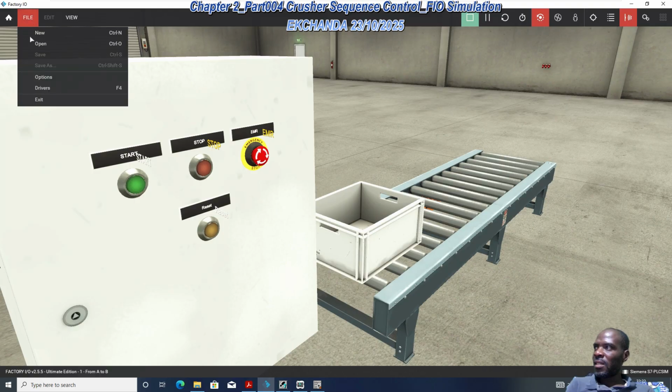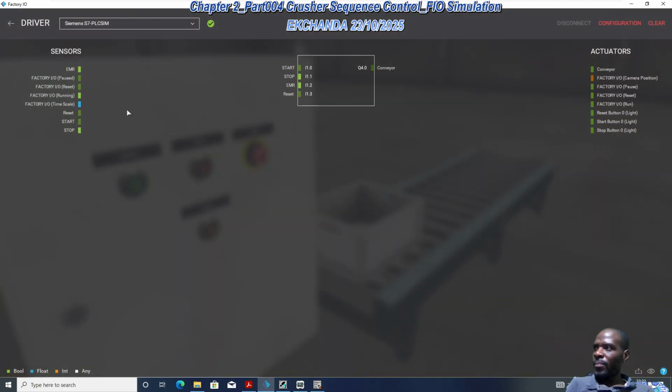If you noticed here, okay, if I press the emergency push button, it sustained the change in state, okay, unless of course I reset, then the status is normalized, as opposed to a push button, the normal system stop. Once I release, even the signal state resets. Okay.